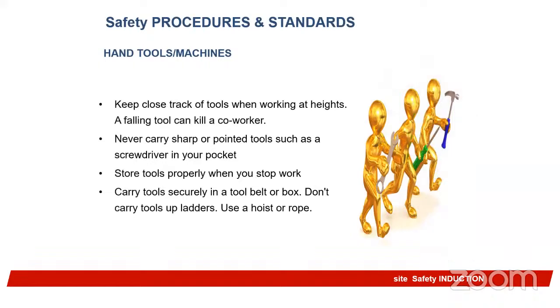So also you talk about, there are so many things to talk about when you're talking about hand tools. Keep close track of tools when working at height. A falling tool can kill a co-worker. So you should always grip your tools properly. You should have what we call a tools lanyard around your waist, so that in case it drops off from your hand, the tools lanyard will hold it and not allow it to fall to the ground.